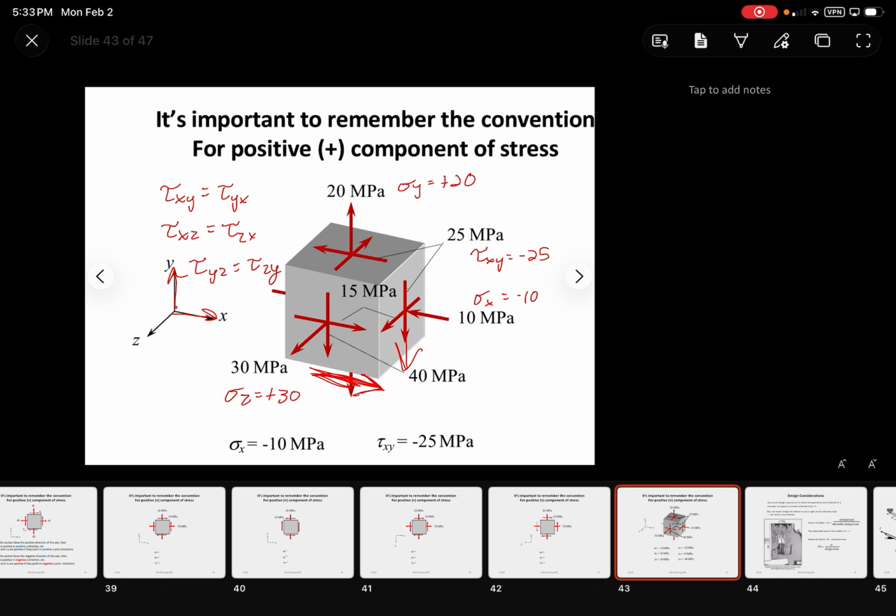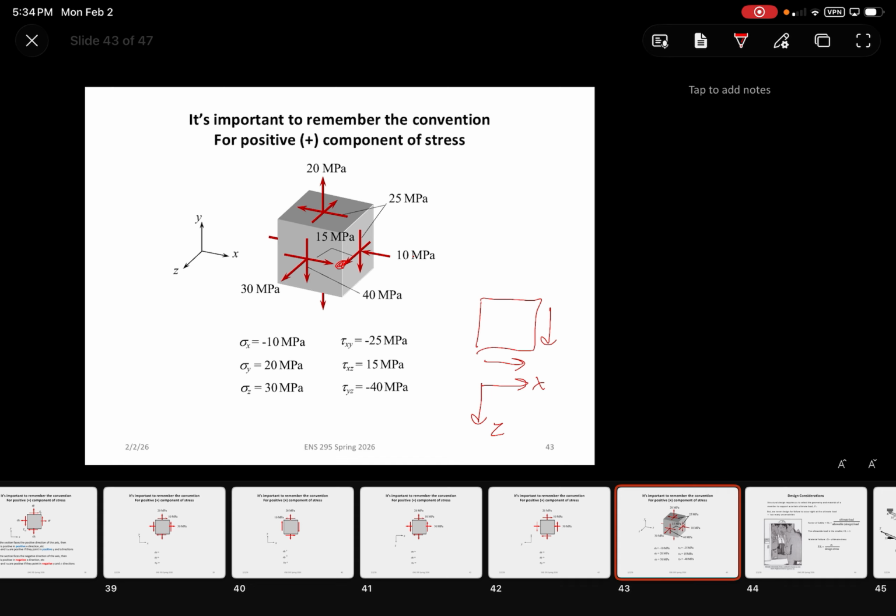So on a 2D plane, even though there's like 8 vectors, there's only 3, you get an X and a Y for normal stresses, and then 1 shear stress. There's basically 3 normal stresses and then 6 shear stresses, but 3 of the shear stresses equal another 3 of the shear stresses. So you only technically have to really put down 3 normal stresses, 3 shear stresses. For 3 dimensions, right? Yeah. For 2 dimensions, it's like you cut that in half and it's only 2. You would only have 3, sigma x, sigma y, and then a tau xy, or whatever planes you're dealing with. Does that make sense? Yeah, and they point towards the pointers. Exactly. Yeah, the shear stresses are always going to point towards the corners.